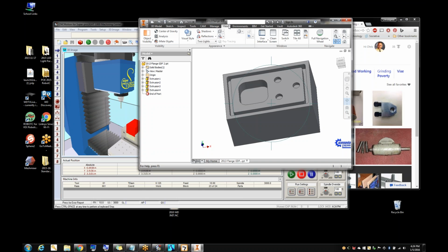It's just on the very last tab of the contour, you have to take away, shoot, I don't even remember what it's called. You want to show your screen, Jim? I'm looking on my screen. It's called the lead in and lead out. You have to uncheck the lead transitions. If you take those away, then it should fix your problem, if your problem is what I'm thinking of off the top of my head.